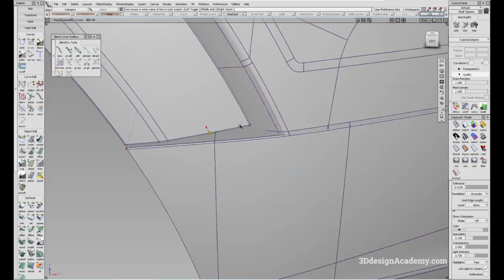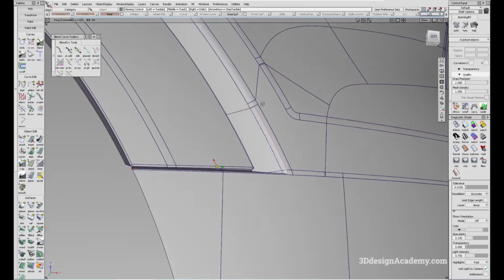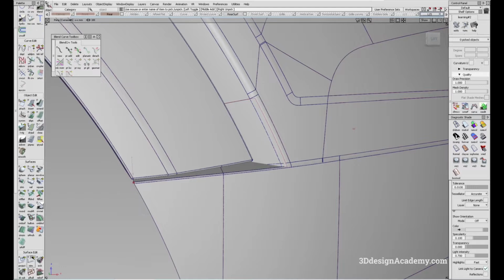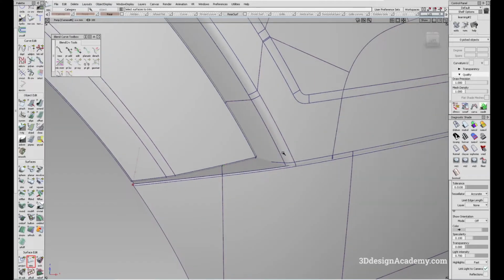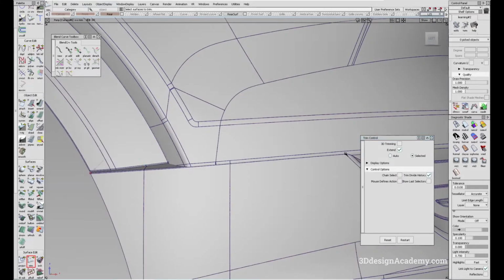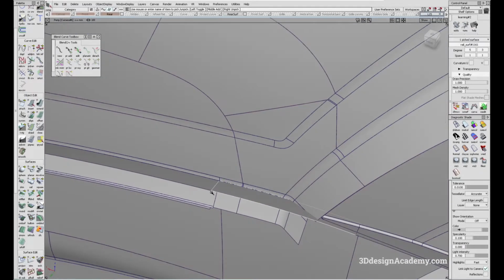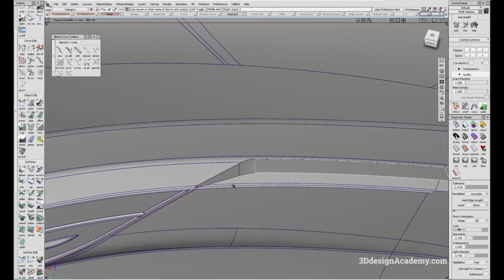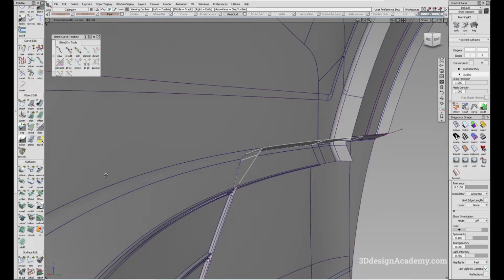Okay, so continuing from the previous lesson, I'm just going to be working on some minimum fillets and gaps and flanges. So let me just trim this piece over here. I'm just going to extend like this to trim this piece, and I think I'm going to put a little gap over here. For this one, I'm just going to be putting a 1 mil gap. Now, because I don't think this is actually drafted, I'm just going to be doing just a straight offset.